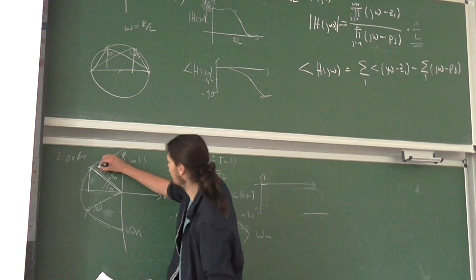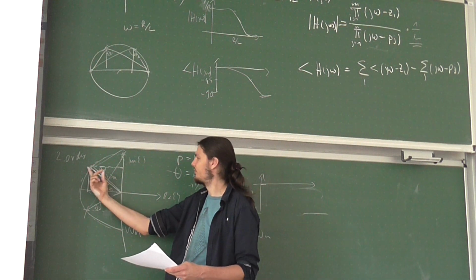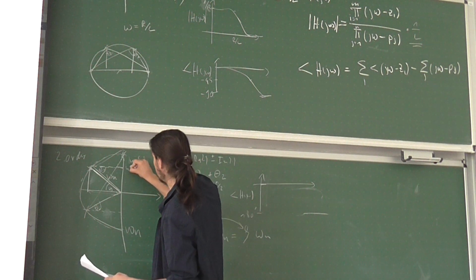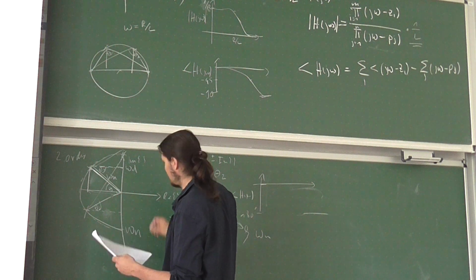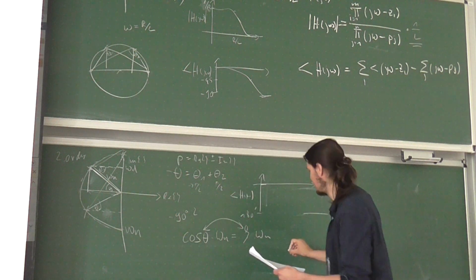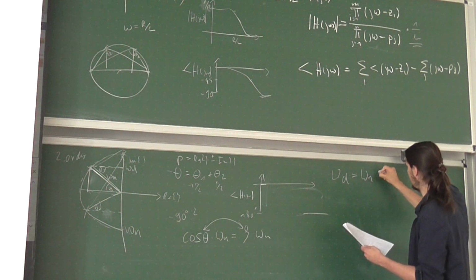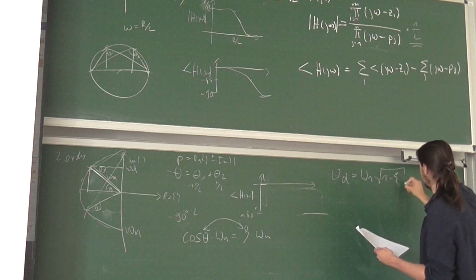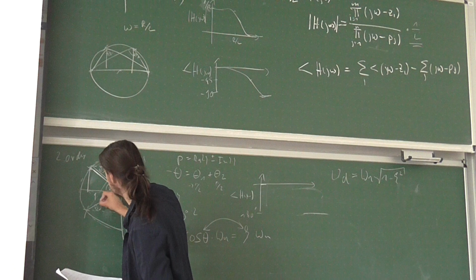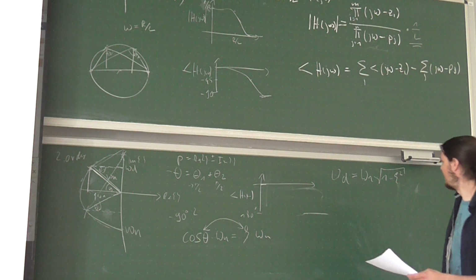And then we also have this point here, which basically, when you project just the imaginary portion of each pole, Omega exactly. People very often call this omega d. And omega d basically equals omega n times the square root of 1 minus zeta squared. Because this is the omega n down here, and you can do the Pythagorean theorem yourself, and you will have this.